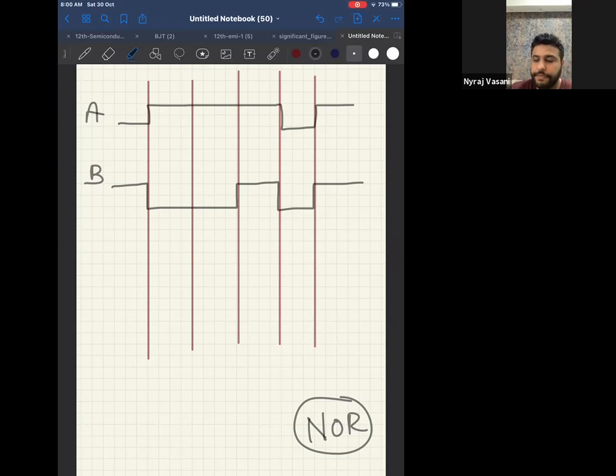Okay, now listen. If I go to draw, this will be 0, 1, 1, 1, 0, 1. And this will be 1, 0, 0, 1, 0, 1. Correct? So now NOR gate. Now the best way to do it is OR gate. 0 and 1 OR gate would be 1. So NOR gate would be 0. 1 and 0 OR gate would be 1.